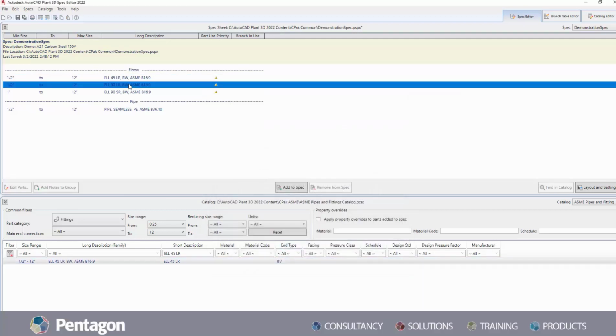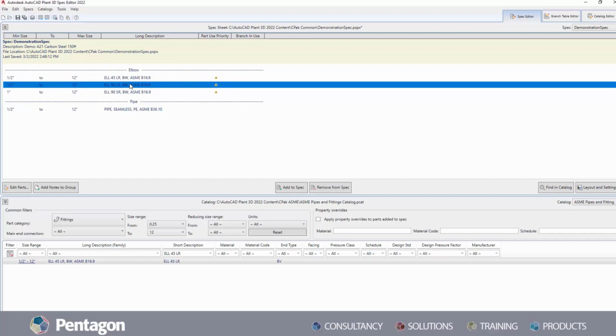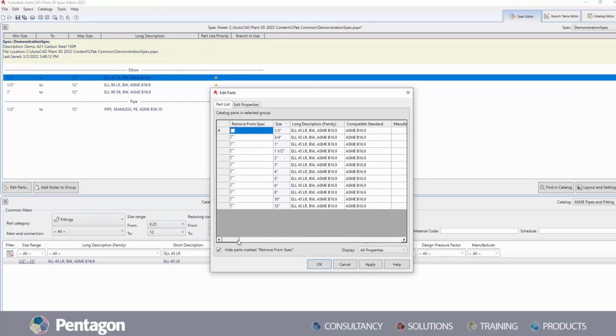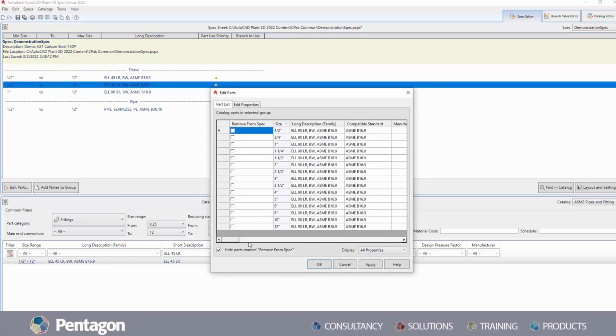So I'm going to keep doing this for each of my elbows because I know the specification that I'm using, these sizes are more or less not out of the box sizes, so they're not going to be applicable. I want something that I know on my spec sheet is available and is there, and I want to be able to route with.